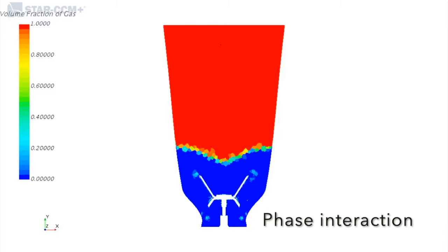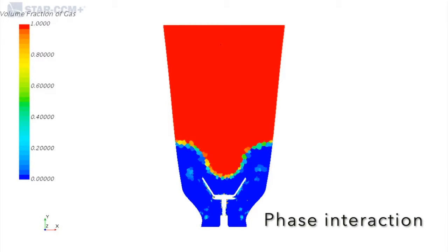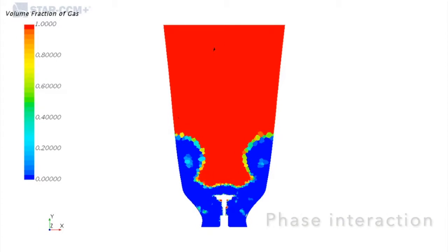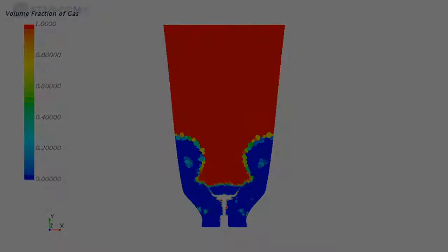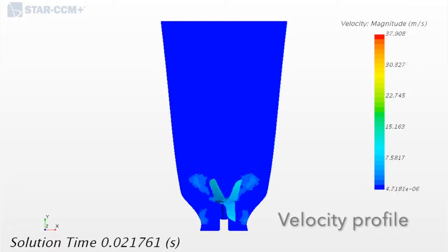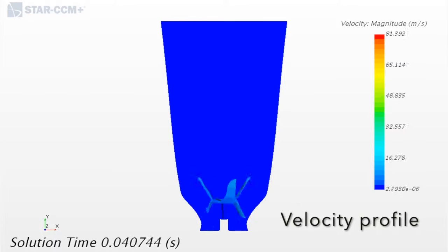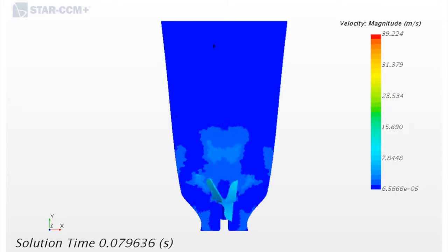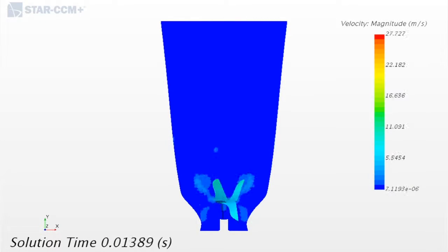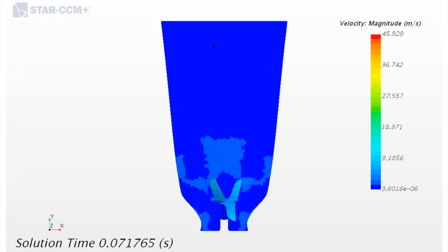In the volume fraction for a stirred tank without baffles, as shown in the animation, the velocity profile of the fluids tends to be organized, which creates the vortex. As the blender starts its motion, the velocity profile immediately shows an increase in its magnitude in the areas around the blades. Due to this increase related to the rotation of the blades, a momentum transfer is shown around them in which velocity increases outwardly.